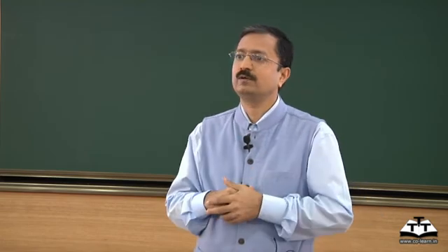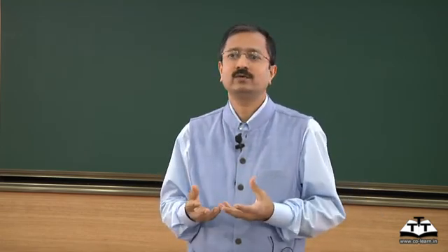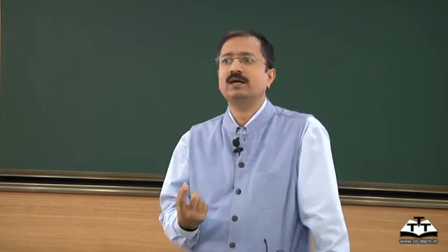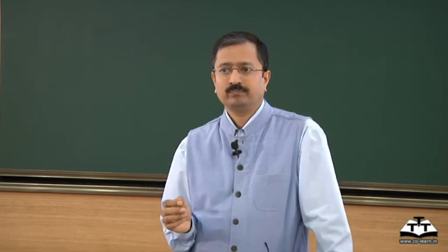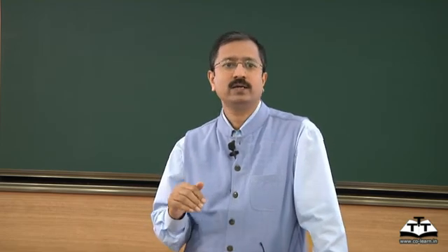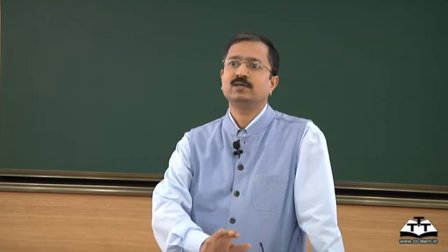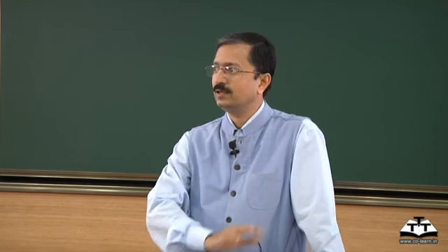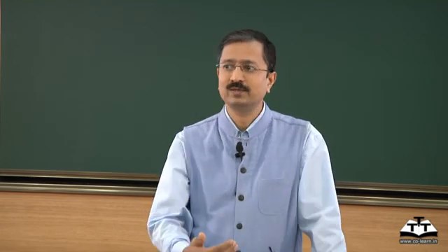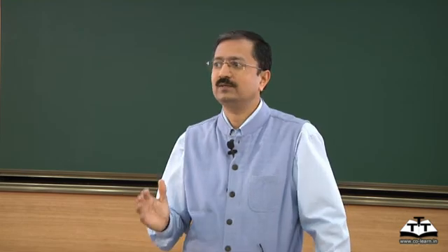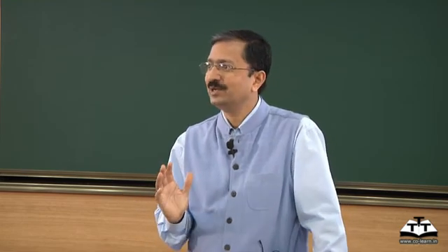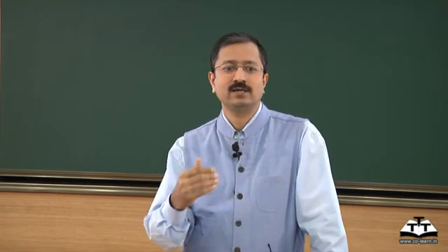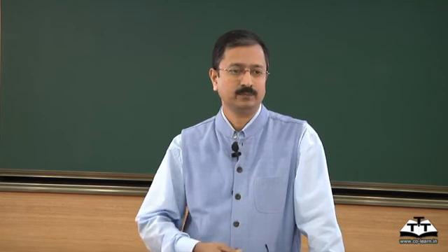And the other one we talked about before was how to reduce manufacturing cost by reducing the number of trials on the shop floor. If you can get the casting right with just one trial on the shop floor, life is very good. And secondly, if I can reduce my rejections from whatever I am to, let's say, target half of that in the next 2 years, and then half of that in the next 2 years, and keep going, if you can reach below 1% in 5 years, 10 years time, fantastic, for jobbing orders, not for regular production of the same part. If you can do that, it's great, and that's the road to go towards ppm level rejections.